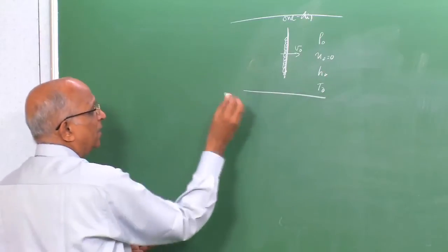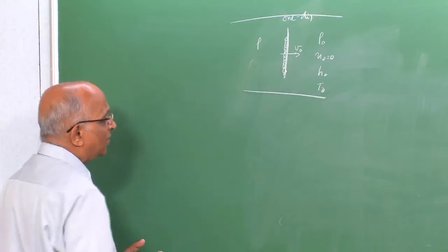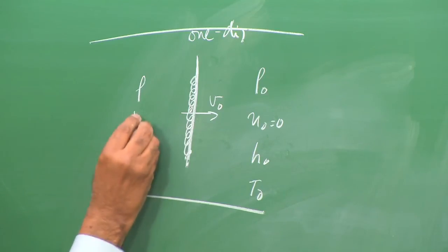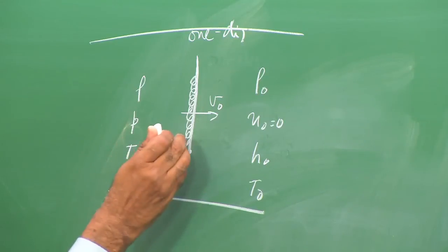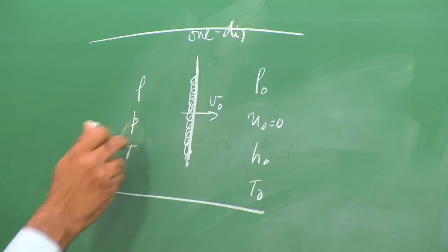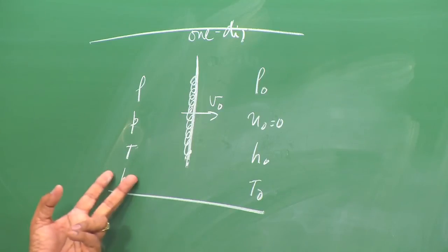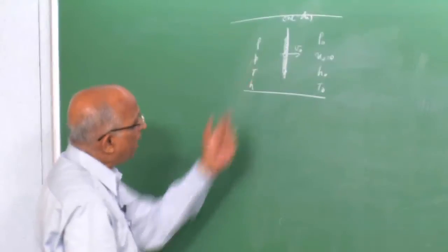What is happening behind the wave? Well, the density has increased, we will work out the density increase in the next class. We will also work out the pressure increase behind the detonation. The temperature is also high because chemical reactions are occurring, the temperature behind the shock itself is high, plus you have chemical reactions occurring. Let us say that the enthalpy here is h. I would like to have a model by which I can calculate the velocity of a detonation. Therefore, to be able to do that,